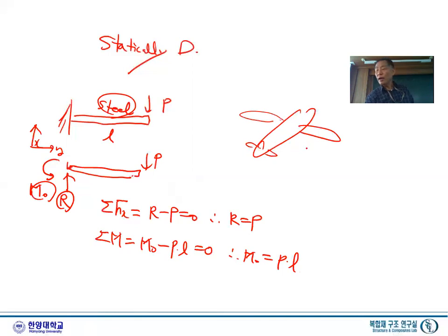All the loads are from this aerodynamic load, right? And all the load is self-weight or passenger weight. So it's a force-wise equilibrium. If we look at this wing, it can be simplified like that. Well, this is a little different from this, but conceptually very much the same. So we can say this one is the P. Again, all the reaction force is determined by this length and this force.